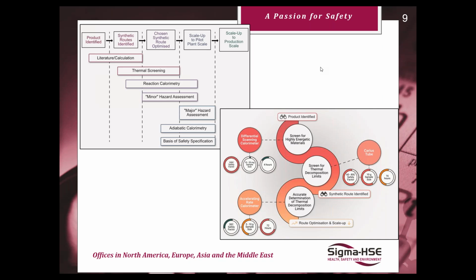It's about this point you start doing some of your assessment. If this is for a new process, you may not know exactly what your plant and services look like at this time if you're setting up a new reactor. So the minor hazard assessments need to look at the feasibility of the reaction itself.